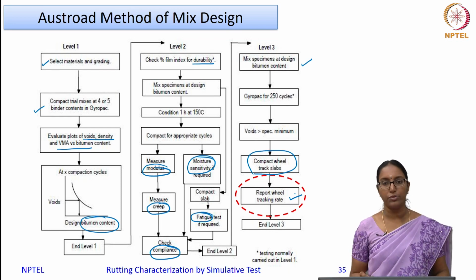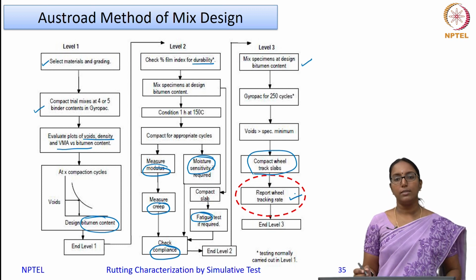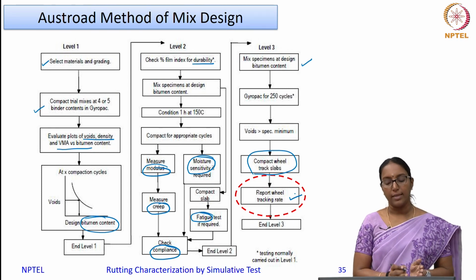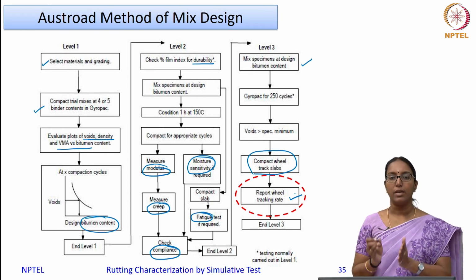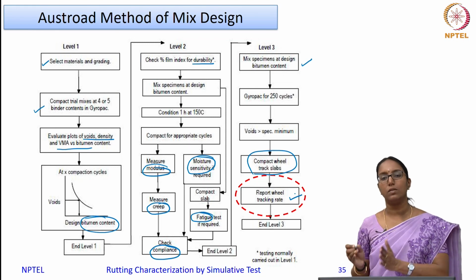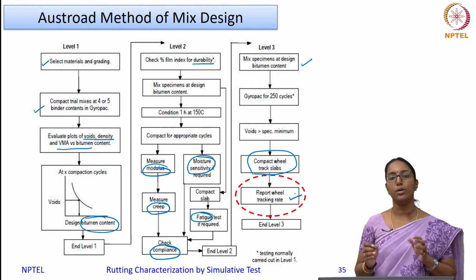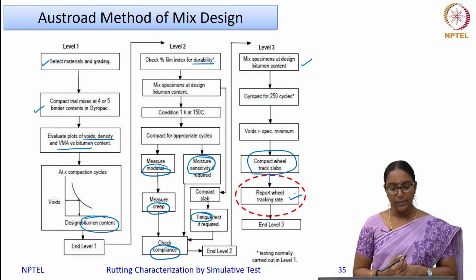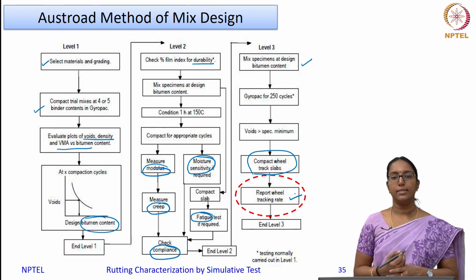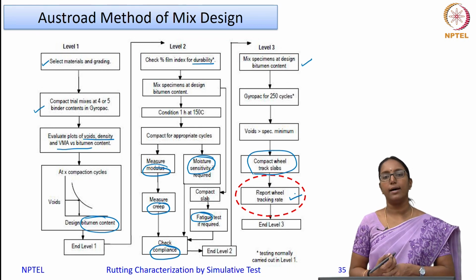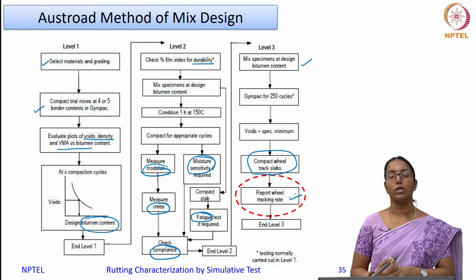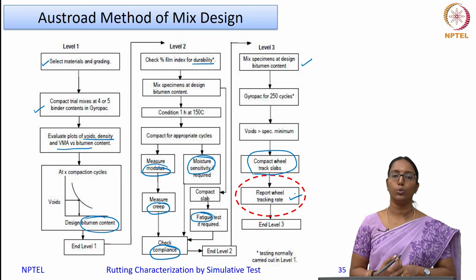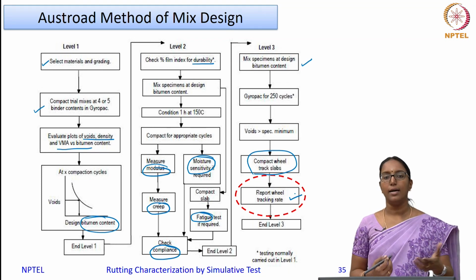So this is a whole procedure wherein you consider the volumetrics, and in addition to the volumetrics, the various durability and strength parameters are also taken into account for designing the mixture. With that I conclude this lecture. We will continue with the other bituminous mixture testing, the performance related testing like the flow time and flow number test, in the upcoming lecture.